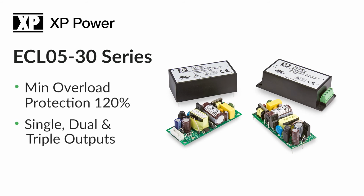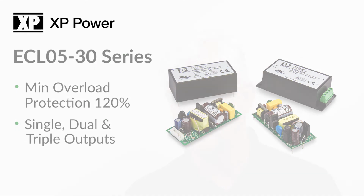Finally, for situations where small peak loads of 10 or 15% are anticipated, it is possible to exploit the margin provided in the specification between the output current rating and the lower level of the overload protection. Provided that the average power demand is kept below the output current rating, occasional peak power demands can be fulfilled while keeping the size and the cost of the power supply down. Here is a very useful example. The ECL series, with models between 5 and 30 watts. The overload protection starts at 120% of the output current rating in this family of products.